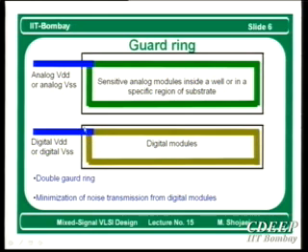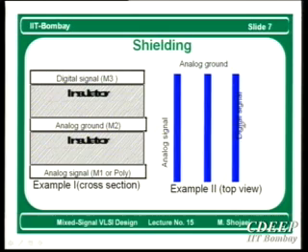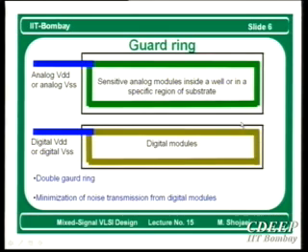For example, if this is an N well and this is an N plus, and outside this P, you put a P plus also here. Therefore, now you will have a double guard ring, so that is much better. So always put a guard ring.